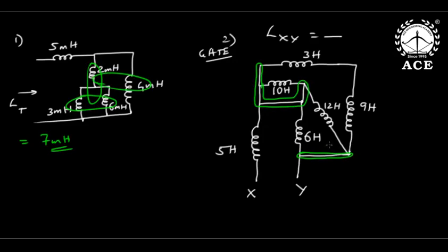Okay, this is one single node, and this entire thing is also a single node. But current cannot flow here, right? Yes, current cannot flow here. Please understand, this is one single node, and this is one single node, and current cannot flow here. Because the inductor is also shorted, it will be bypassed, so it won't work. So this I can remove. Okay? Yes, that is the meaning.